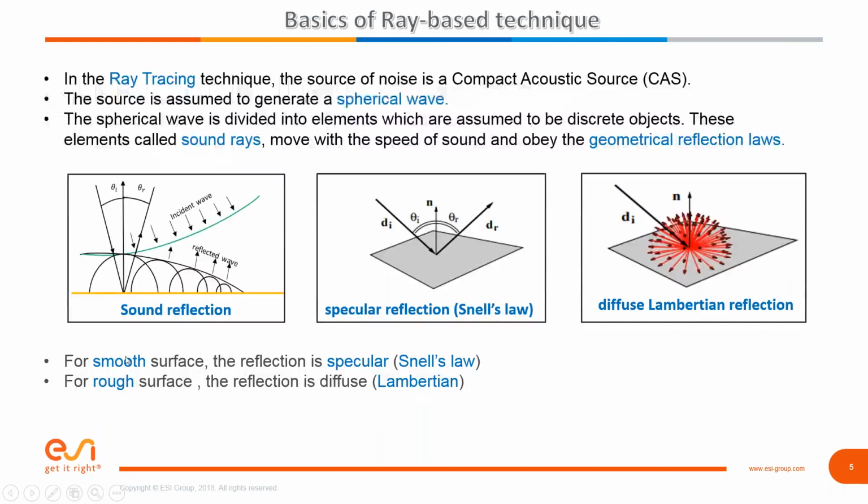So we already have two options that I'll come back and discuss later, but it's enough to know that for the rough one, you have more scattering, and the main energy comes out at an angle that doesn't have to be identical to the incident angle. We have a distribution function at which that ray can propagate, and it's likely to come out close to the incident angle, but doesn't always come out. It can be modified plus or minus a couple of degrees, and you get some statistics in. That fits well if you have a coarse or more approximate geometry where a literal interpretation doesn't really make sense for that kind of model.